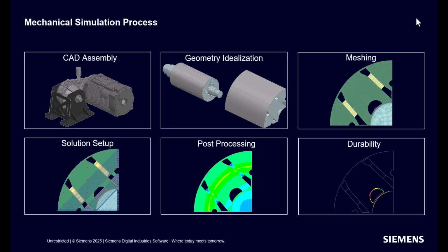That is followed by the definition of multiple steps in the solution, including press-fit assembly of the rotor onto the shaft, the addition of meshes at specific analysis steps, the application of an operating temperature and an operating rotating speed. Basic post-processing of results such as displacements, temperatures, and contacts are highlighted as part of the review of the multi-step nature of the model. User-defined results such as stress margins computed with temperature-dependent yield strengths are performed with result probes.